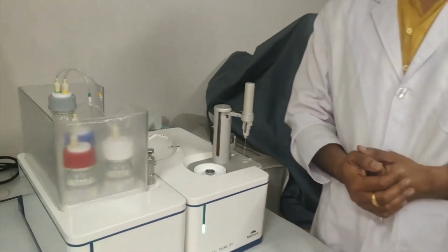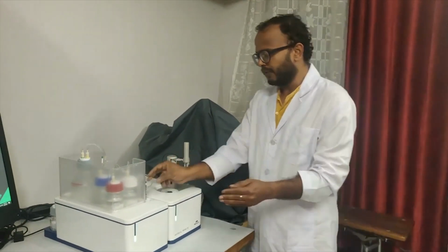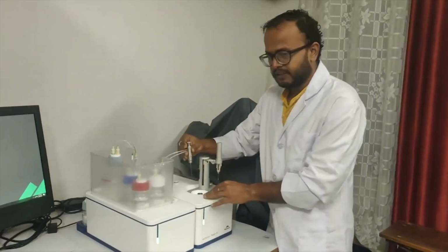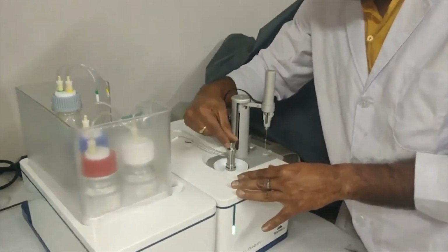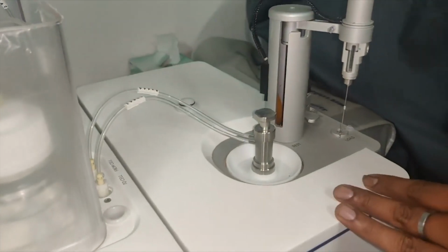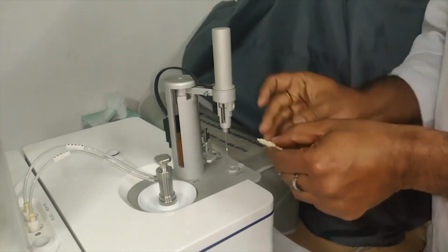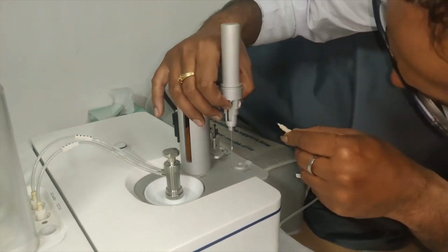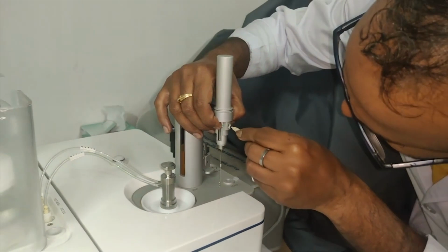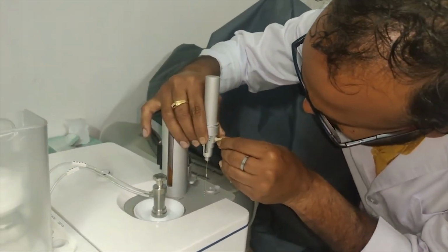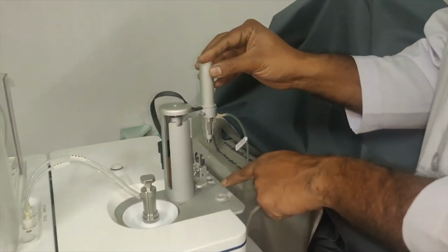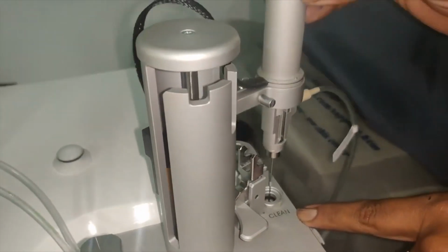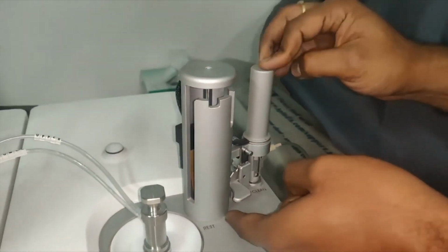Now I will explain how to clean this instrument. For cleaning, first we need to put this cell cleaning tool into the cell and ensure that it is nicely fitted. There should not be any leakage. And then for the syringe, first we need to put this fill port adapter into the socket provided here. It should be firm. After that, we should move this syringe into the clean location, where it is written clean. We will move it slowly and ensure that this clamp is nicely engaged here.